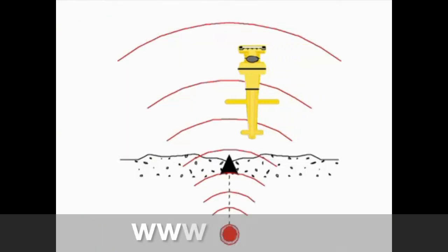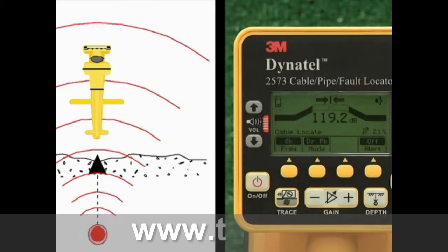The numerical signal level should be at its highest value, the bar graph should be almost closed, and both arrows displayed when locating a target with an undistorted electromagnetic field. See Advanced Application Techniques for information about measuring the symmetry of a locate signal.